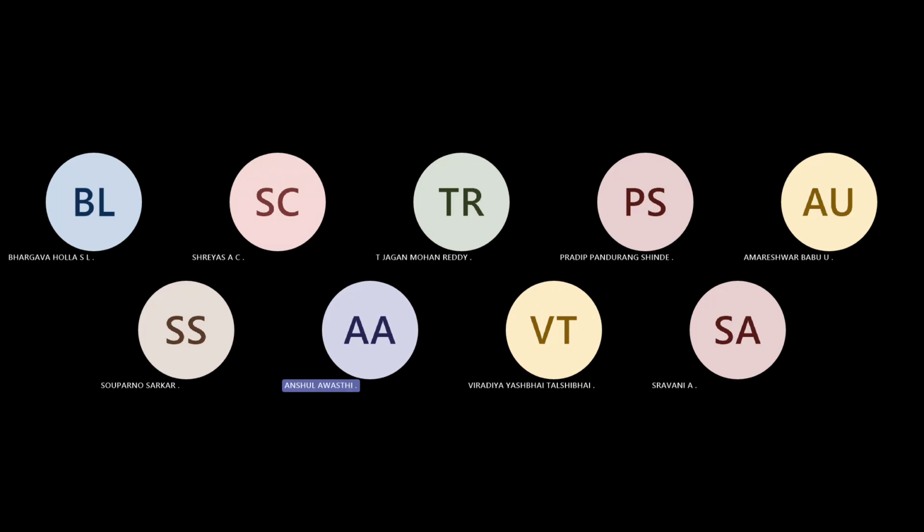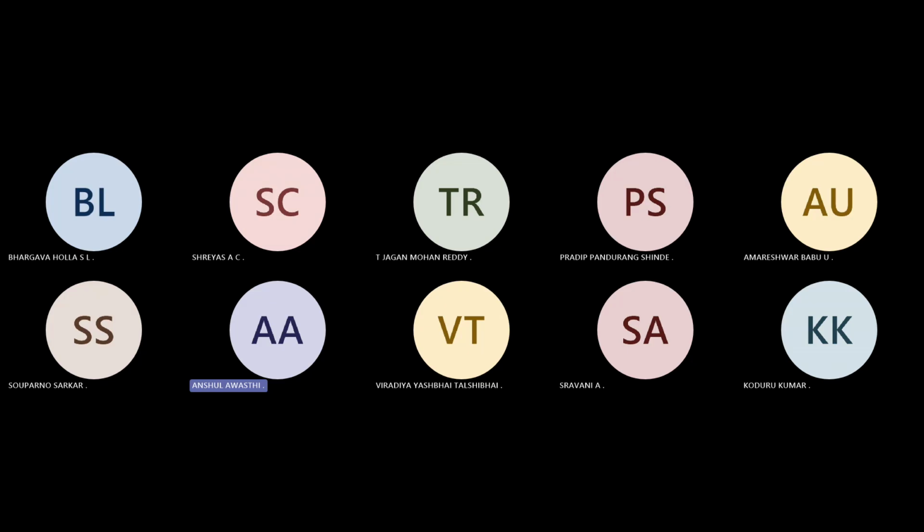If you have noticed in the last experiment, for each and every variation, we have to change the value and again run the simulation. For example, if I want a plot for ID/VGS for, let us say, VD equals 0.5, I have to make VD equal to 0.5 and run the simulation. So I'll get a curve of ID/VGS for a different VD. Similarly, if I want a similar curve for VD equals 0.7, I have to again manually change that value and run the simulation. So this is a tedious job.